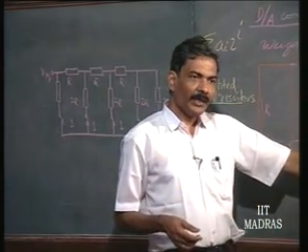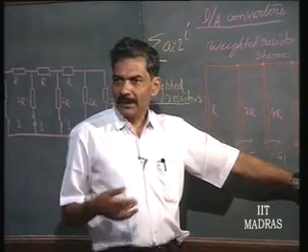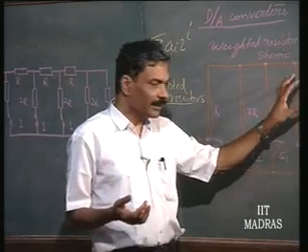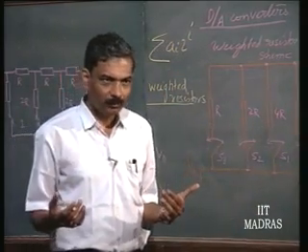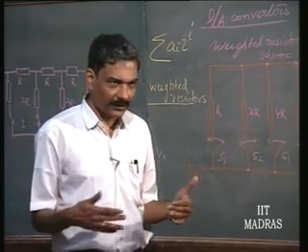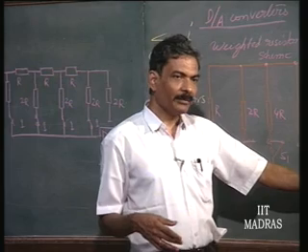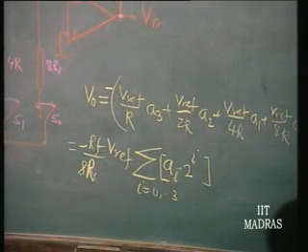And you might have to go for a ratio of capacitors, which has a better temperature coefficient effect. That means this weighted resistor scheme has to turn itself into a weighted capacitor scheme. Those will be switched capacitor networks. And we have to have a precise V reference voltage.